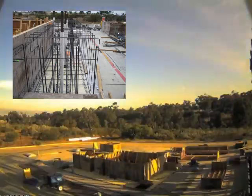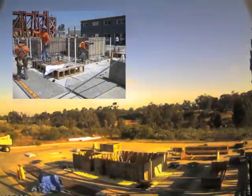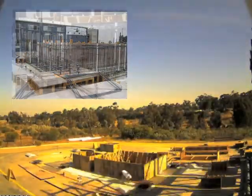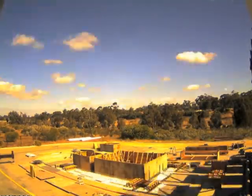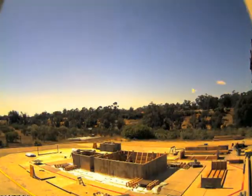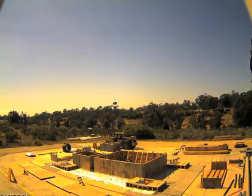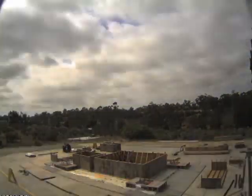After the construction of the foundation formwork is complete, steel reinforcing bars are connected together in different directions to form rebar cages. Rebar cages provide tensile strength for the concrete in more than just one direction, as opposed to rebars laid at one single dimension. These cages can be built either on or off-site and then placed inside the foundation formwork. In this project, the foundation rebar cages were built on-site.